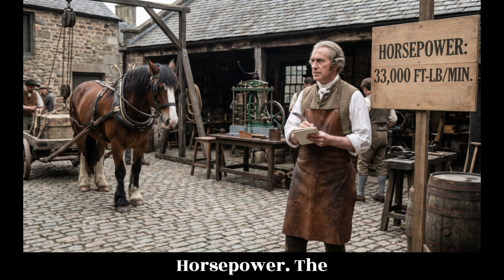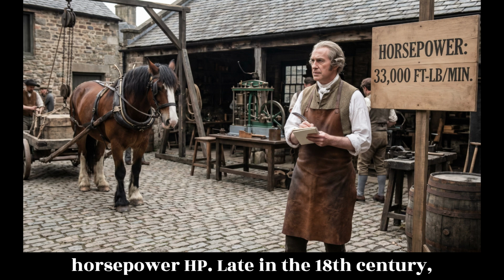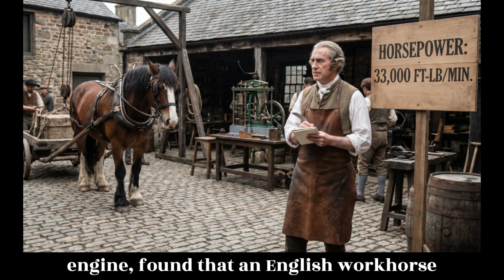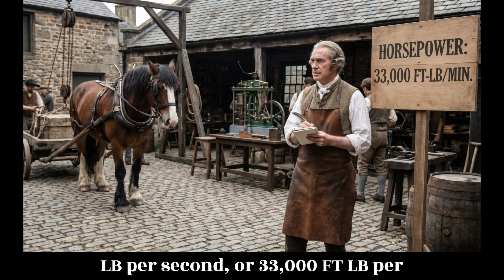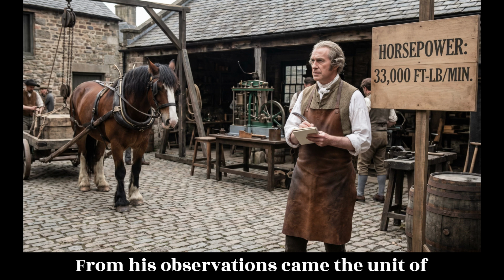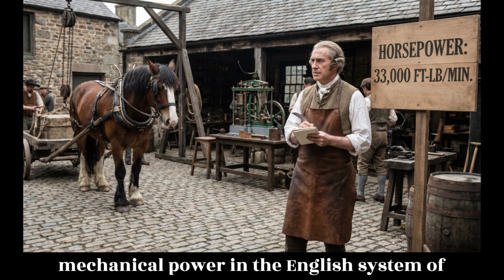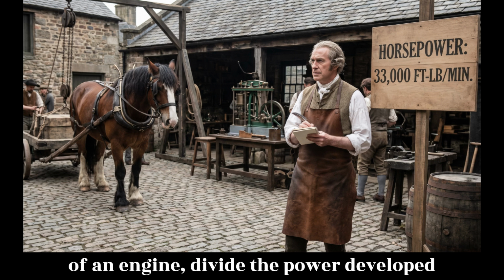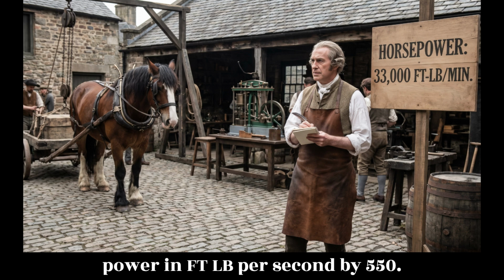Horsepower. The common unit of mechanical power is the horsepower, HP. Late in the 18th century, James Watt, the inventor of the steam engine, found that an English workhorse could work at the rate of 550 FT-LB per second, or 33,000 FT-LB per minute, for a reasonable length of time. From his observations came the unit of horsepower, which is the standard unit of mechanical power in the English system of measurement. To calculate the HP rating of an engine, divide the power developed in FT-LB per minute by 33,000, or the power in FT-LB per second by 550.